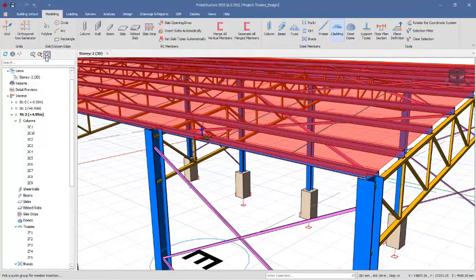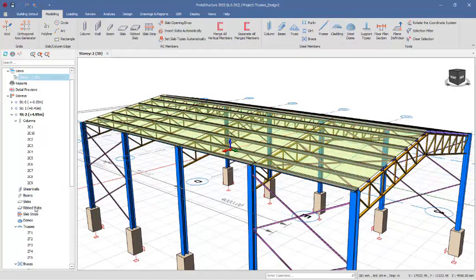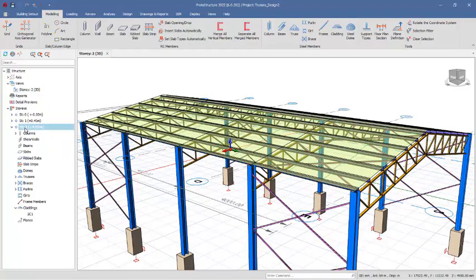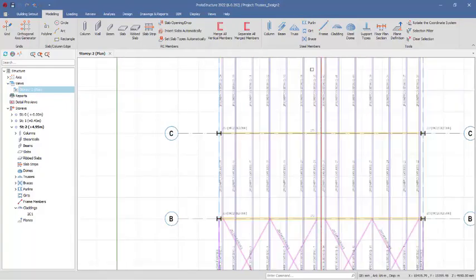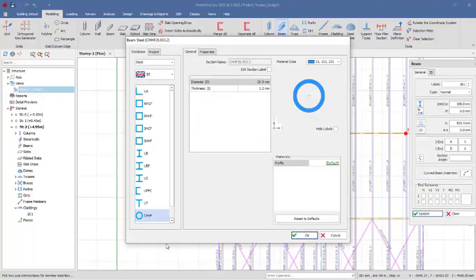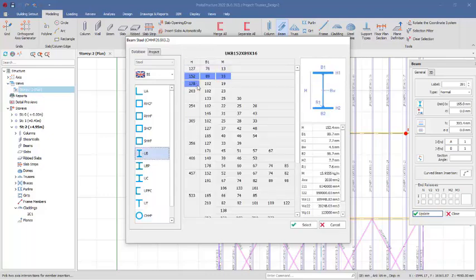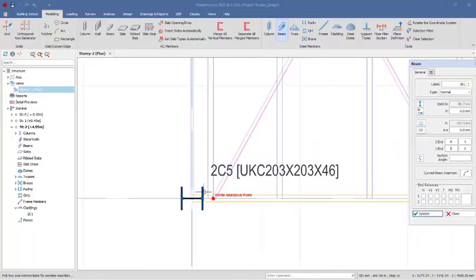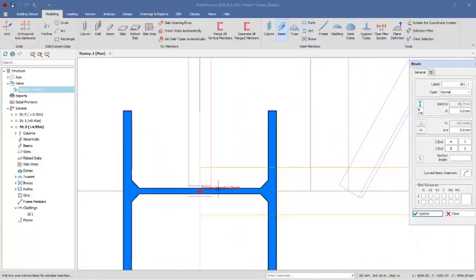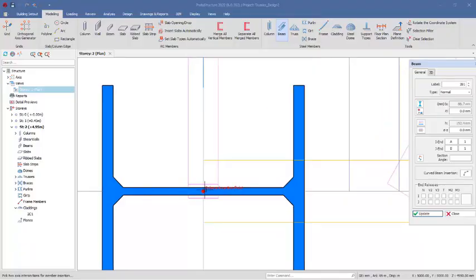stanchions together successfully. So we have to navigate to the plan view of level 2. Okay, we are already at level 2, so get to the plan view. Alright, so in this plan view now, we want to be fixing beams. So the beam, we select the steel beam right there, and then in the dialog you just have to choose one of these smaller sections of the universal beam right there. So we use 150 by 89 by 60, 16 thickness. So click right there and OK. So we have to pick that from one point to another successfully, so we wouldn't want to miss load.